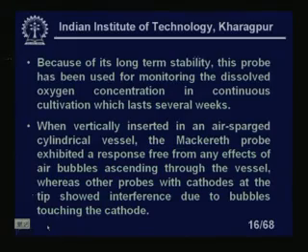When vertically inserted in an air sparged cylinder vessel, the Mackereth probe exhibited a response free from any effects of air bubbles, because the function of the air bubbles is to increase the dissolved oxygen concentration or partial pressure of oxygen in the bulk medium of the liquid, where actually my reaction takes place, right. That is the most important thing which you should consider. That problem does not arise if you use a Mackereth electrode.